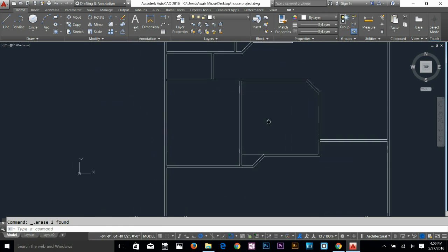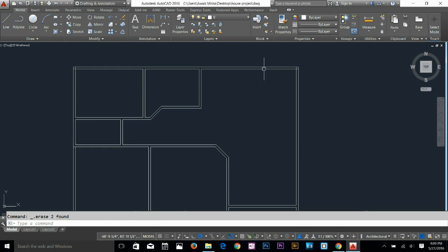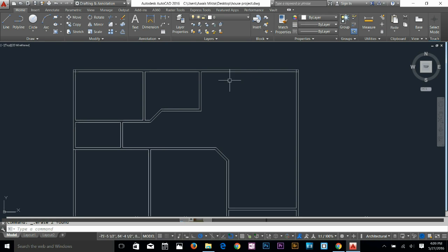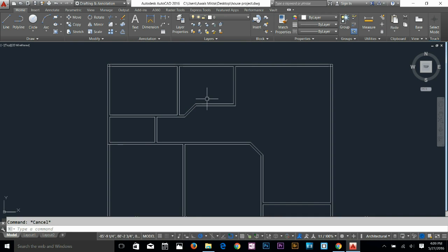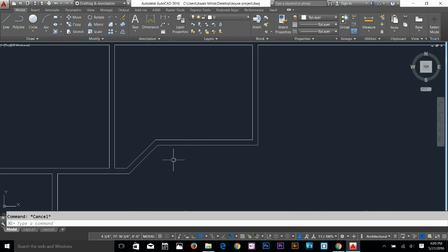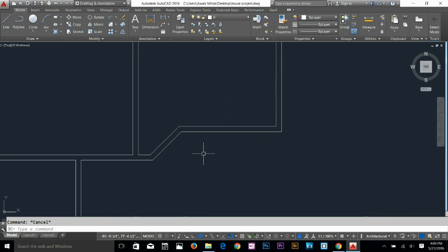Okay, so these things are done now, and what we can do here, it's going to be open living area here, and then this can be a kitchen, and this can be a bath here, and this can be a TV and living area here. Okay, alright, so what you can do here, I want to move these 2 lines. This is kind of really big, so I want to move like another 1 feet. Fillet command to clean up.